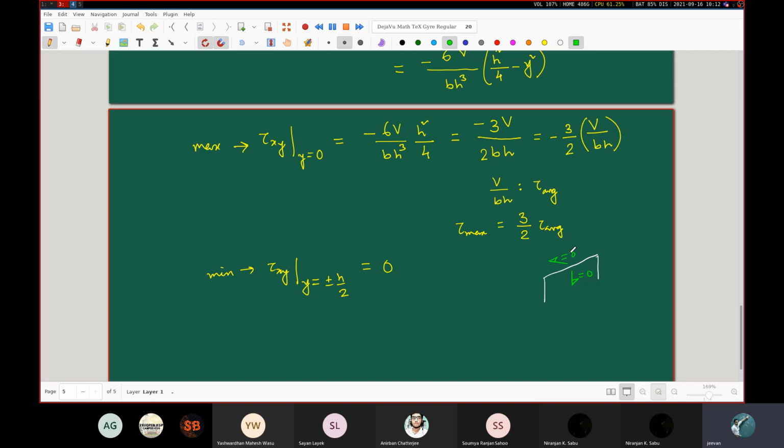So when we use the word complementary in the context of shear stresses, it has nothing to do with pi by 2 minus something like we used to do in our school level geometry. Please note that. This is just a terminology used by people interested in solid mechanics. They just say that the shear stresses on two perpendicular faces are complementary to each other, meaning just that they have different directions, but their magnitudes are the same.